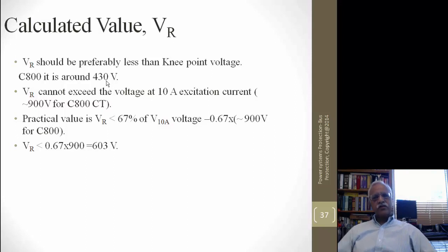So you should not put extremely long cables and then develop it, and if you come up with a setting which is higher than this, there is a likelihood that the CT saturates even for internal faults, and then most of the current goes in magnetizing these cores at these higher voltages.